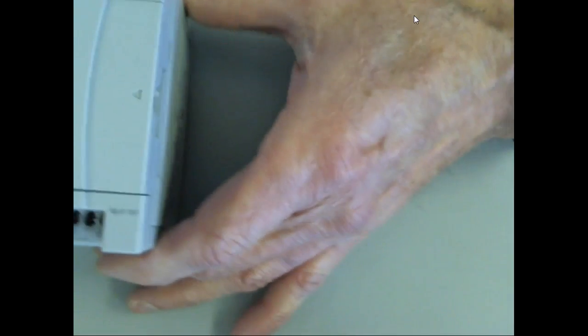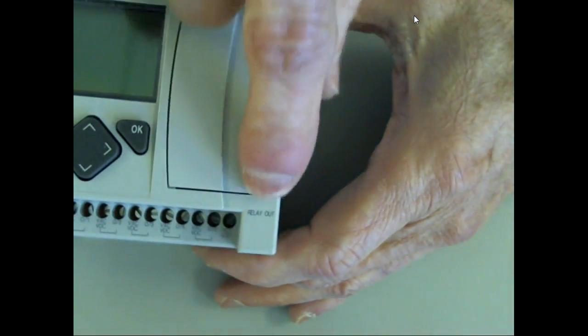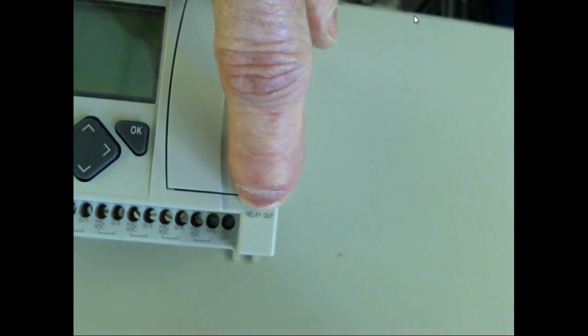And then it says it's got, you read that? Relay out. So we can get different variations of those 3 on our PLCs or our modules. That makes sense? And we'll talk about relay out, which the book don't cover. So if I've got DC input, then we don't need that rectifier. But you'll understand that. So the rectifier wouldn't be on the DC input because that's what it expects to get. The rectifier would be on AC inputs.